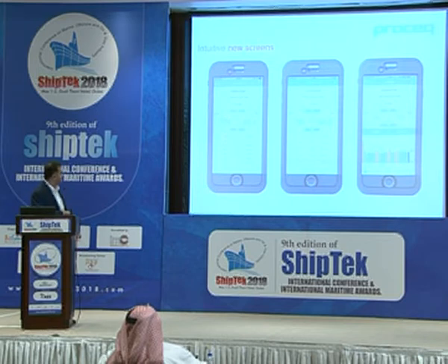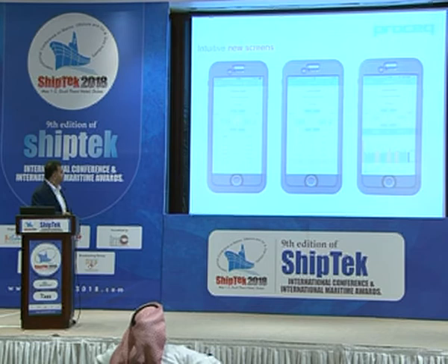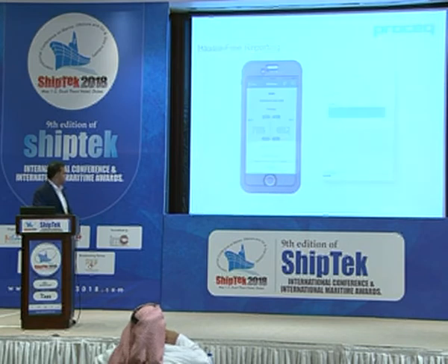So basically we are talking about all the data: average, the mean and total number of tests. All this data is available. The readings are here in HLD and HRC, in two different hardness scales, and basically individual readings are here. We can also see the bar charts. And we can instantly generate the report.